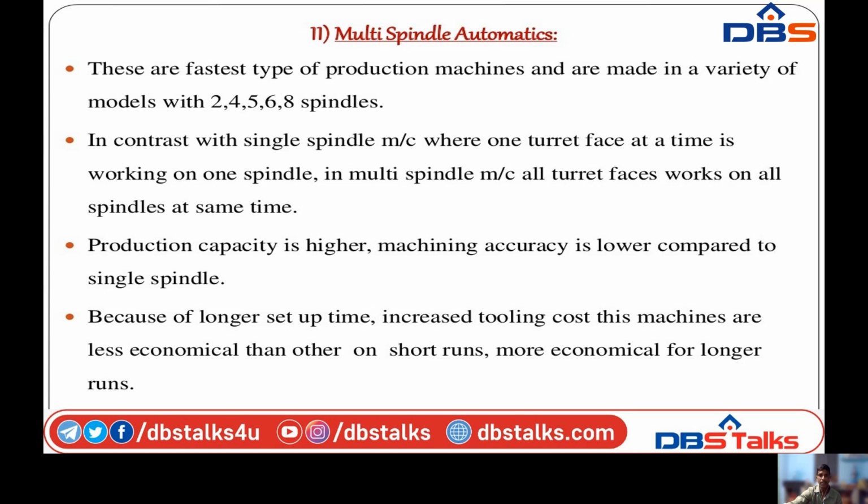lesser than single spindle, because in single spindle we are performing only one work, that means only one spindle is rotating about the machine center. When it comes to multi-spindle, 2, 4, 5, 6, up to 8 spindles, the work is going on. So accuracy is lower, that means small dimensional errors are there in multiple spindle. Because of longer setup time and increasing tooling cost, the machines are less economical than others for short runs.